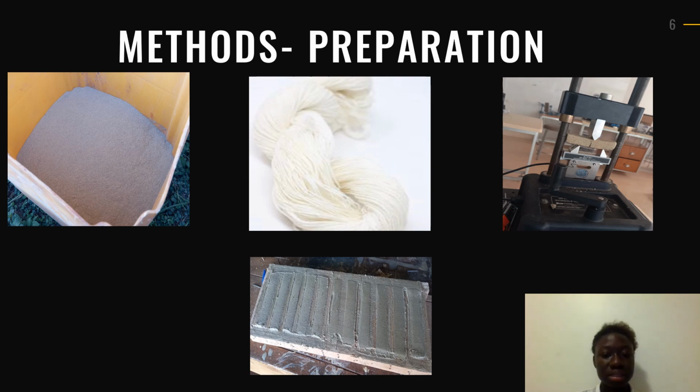And after they were cast, they were left indoors for 24 hours to avoid cracking when exposed immediately to the sun. And after, the samples were left in the sun for 1 week to dry completely. Then the samples were taken to the MEC lab so that compression testing will be done on the cylindrical samples, whilst 3-point bending test will be conducted on the rectangular samples. So the fibers were oriented randomly. That means it will be stronger in either direction, whether longitudinal or transverse direction.